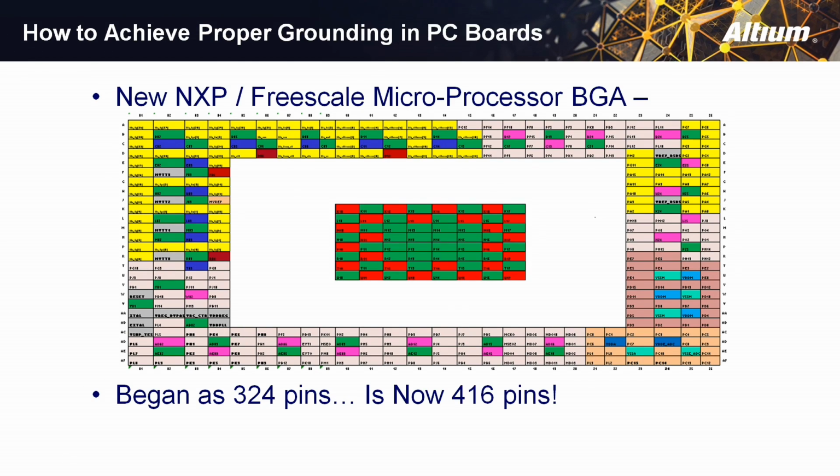And notice that each of the powers is positioned immediately adjacent to a ground signal. Why? Because inductance is dominated by position, not by size. And the reality is position is critical if you expect low inductance. The only way to get low pin inductance is to properly return power to ground.